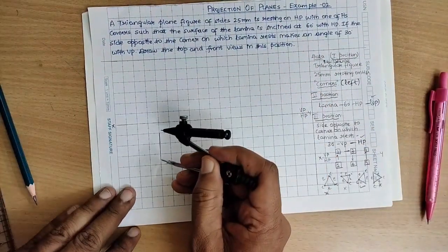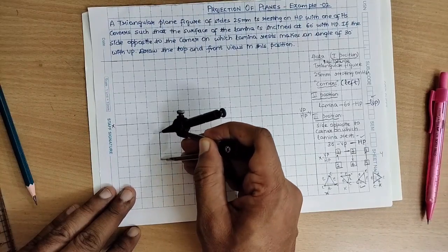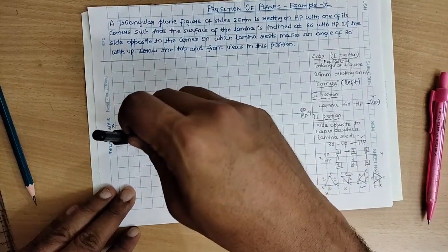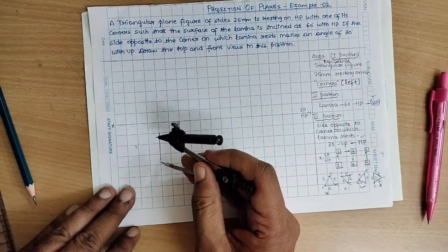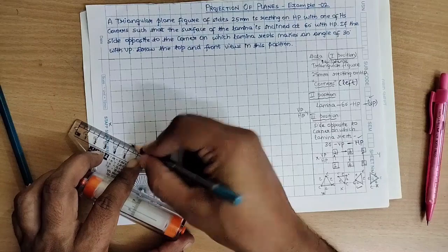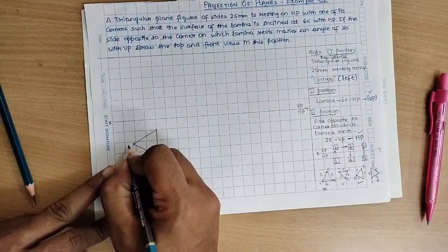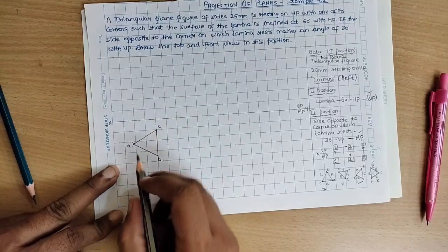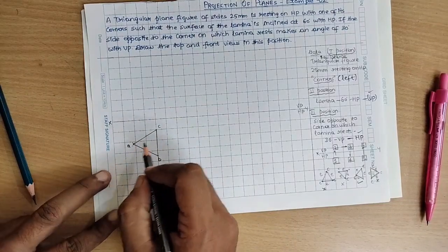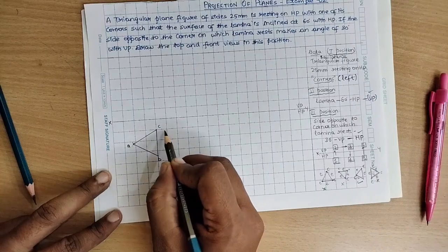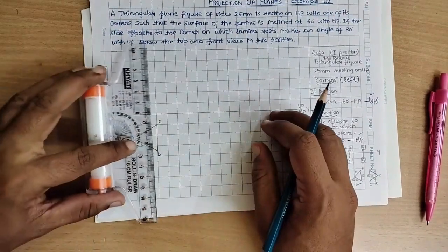Now make use of a compass. Take the same measurement, 25 mm. With this point as the center, cut an arc. With the other point as a center, cut one more arc so that the second arc intersects the first arc we have drawn. Connect to the new corner. Let us call these points A, B, C. Naming is important. You should start from the left extreme bottom corner and move around the geometry in the counterclockwise direction. This is position number 1.